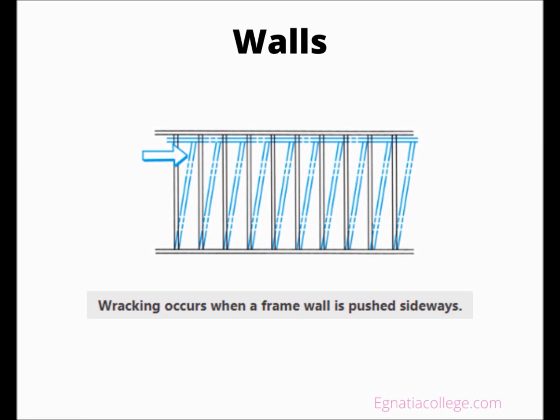The standard shear-resisting method used for walls is to apply structural sheeting such as plywood or OSB, nailed to the studs and plates in a prescribed manner. Because shear walls must resist the forces of an earthquake, the size, placement, and spacing of nails is especially important. In areas with very little seismic activity, it is not customary for construction drawings to specify nailing schedules.